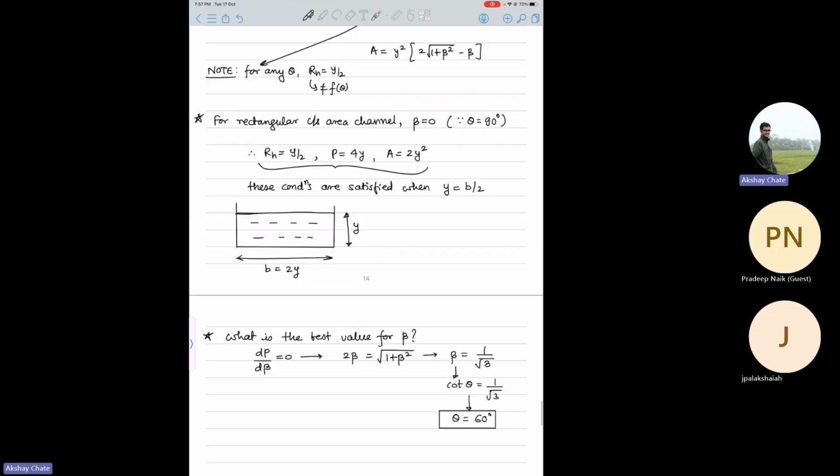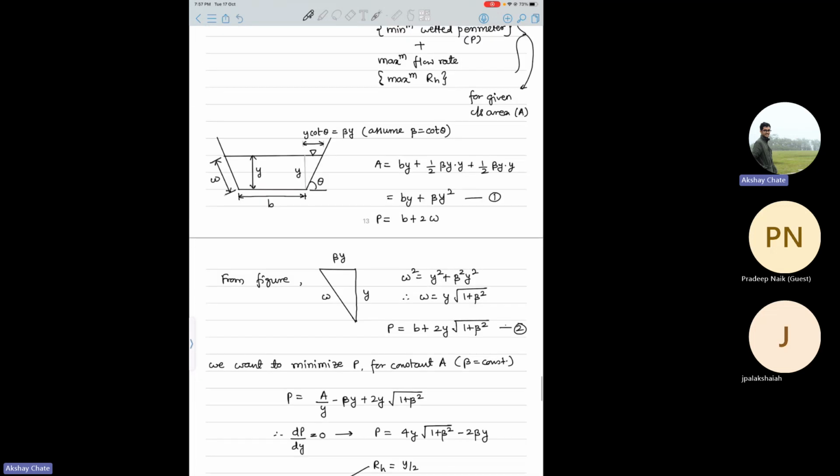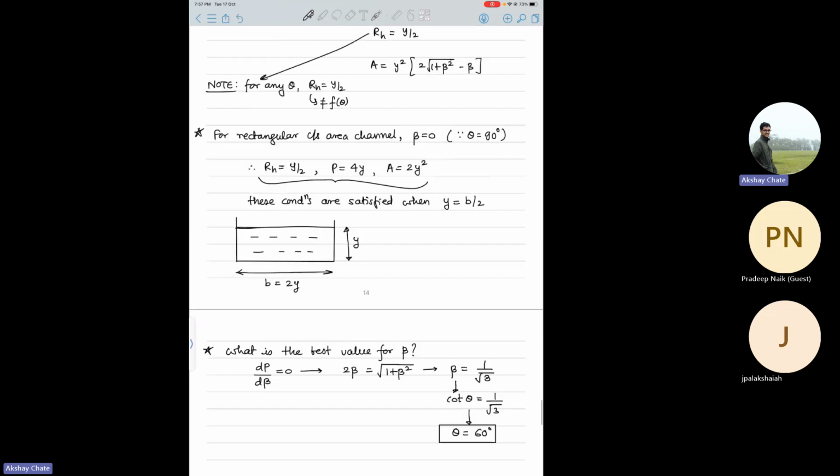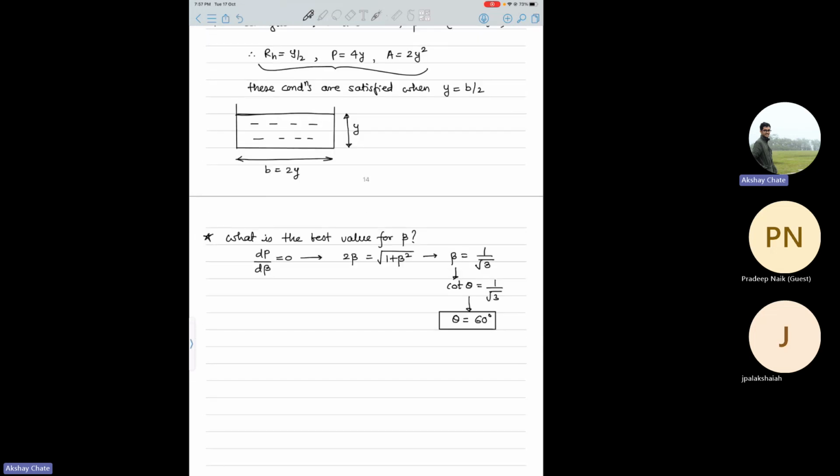So basically when your trapezoidal channel is nothing but a half hexagon, then you will have the best or the maximum flow rate for minimum pressure drop, the efficient trapezoidal channel. You can try for other different channel geometries and you can get the expression like this, but rectangular channel and trapezoidal channel are common. For circular channel also there is such a derivation.